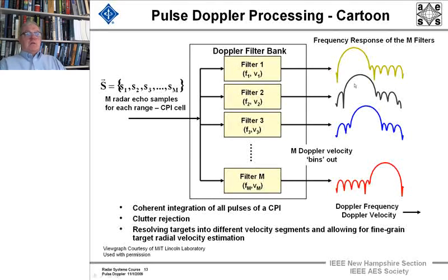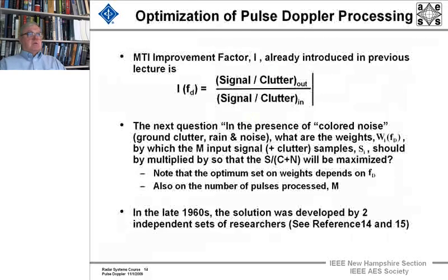And we're going to come out with a number of Doppler velocity bins for each range CPI. There are 2 CPIs per azimuth beam width cell. And so coming out, every scan of that airport surveillance radar is, I forgot the number, in the order of magnitude of 3 million range-azimuth-Doppler cells that come out of it. And we're going to have to threshold those in a manner so that we see the targets, don't see the noise. Back to our detection lectures.